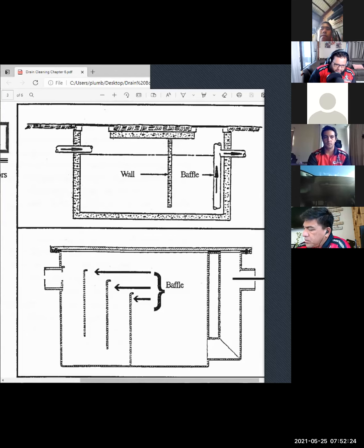That is one way to also diagnose your stoppage. If you pull that manhole at the end of the grease trap and that sample box is full of water, you're not dealing with a full grease trap again. You're dealing with a mainline stoppage past the grease trap. I know some guys like to rip open the grease trap, say it's full to the rim over the inlet and the exit, and then they call the pump truck guy in, say, hey, your grease trap's full, just to find out it's backed up past the grease trap. So do your full diagnostics when dealing with commercial kitchens.